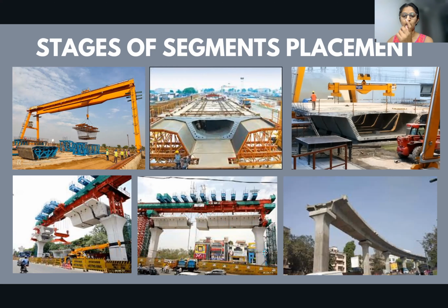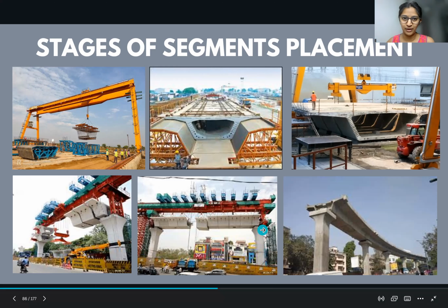So when it comes to concentrating on the pier part, you can have a closer look over here. The segment that is resting on one side of the pier, one half of the pier basically, the dimension of that particular end segment will be a little small, because one pier cap will be bridging from one span to another. So that is where all of these segments will be coming into the picture.